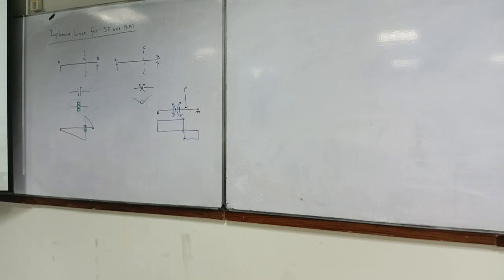You can also do something like, if you want to derive or draw your influence line diagram from first principles, what did I tell you? You can have a load moving and you keep on finding your shear at different locations and keep on populating all these magnitudes, and you will get an influence line for shear force.